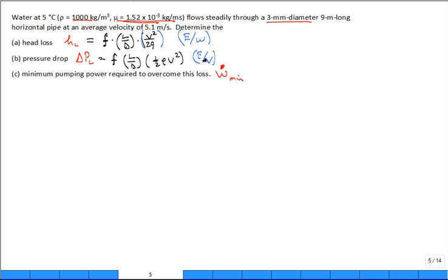Yes, sir. All the other terms are there. The length, the diameter, the V squareds are given to us, and we know g if we need it. But f, how do I get f? Okay, I'm thinking in my mind Moody diagram. Lower than 2,000, I have an analytic expression for the friction factor. Above, in the turbulent region, I may need to use a correlation or just use the Moody diagram, so I need to find f. So I calculate the Reynolds number for this problem.